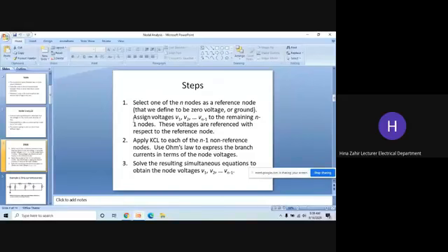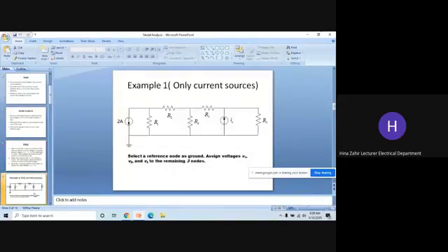First of all, when we are given a circuit and we are asked to apply nodal analysis on it, we will identify the essential nodes. How many nodes are there? For example, we have this circuit. So when the question is nodal analysis, what will I do? First of all, I will say how many nodes are there. This is node, this is node, this is node. We do not consider the bottom nodes, but yes, the bottom has a reference, one reference. If you see, all these wires are connected to this one wire. So this is our reference node.